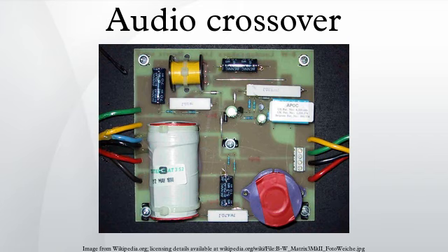A first-order crossover allows more signals of unwanted frequencies to get through in the LPF and HPF sections than do higher-order configurations. While woofers can easily take this, smaller high-frequency drivers are more likely to be damaged since they are not capable of handling large power inputs at frequencies below their rated crossover point. In practice, speaker systems with true first-order acoustic slopes are difficult to design because they require large overlapping driver bandwidth, and the shallow slopes mean that non-coincident drivers interfere over a wide frequency range and cause large response shifts off-axis.